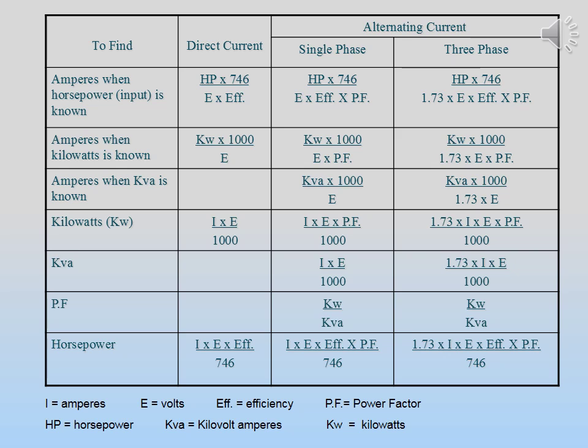This is not about efficiency. It is about how effectively our equipment is using the power that has to be at the electrical pole to provide us with the electricity we need. Just keep in mind that a perfect power factor is 1. Anything less than 1 or more than 1 means there is something that is a little out of balance. However, our power company can penalize us for having a poor power factor because we are not effectively using the power they must have available for us.